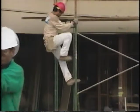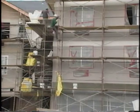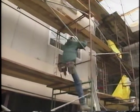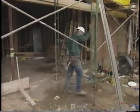Many injuries occur when workers get on and off the scaffold or move from one platform to another. Always use the proper ladder or stairs. Do not climb the cross braces or jump from one platform to another. Jumping increases the risk of injury and creates unnecessary force on the planks.